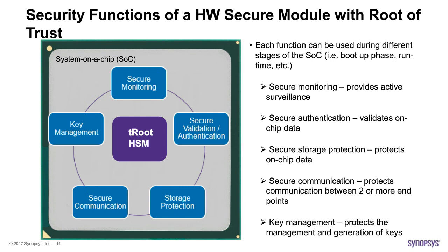For example, you can use a TLS protocol to do so. The master and session keys, which are part of the protocol, are generated inside the hardware secure module, therefore providing protection from any on-chip attacks. So this is typically available only during the runtime stage of an SoC.